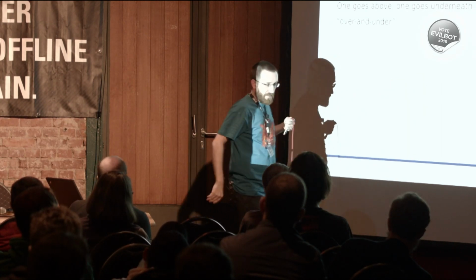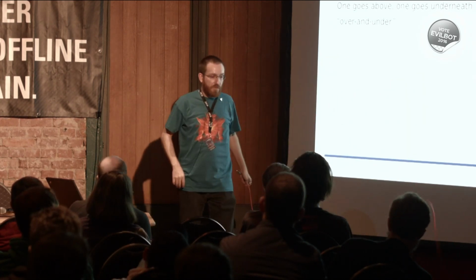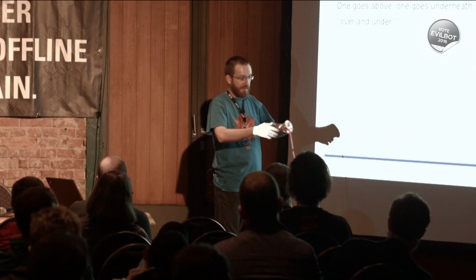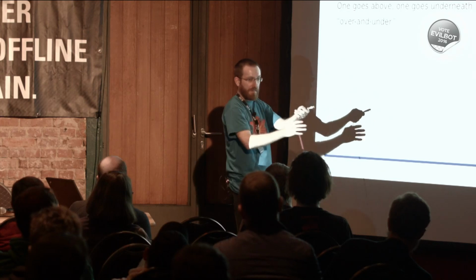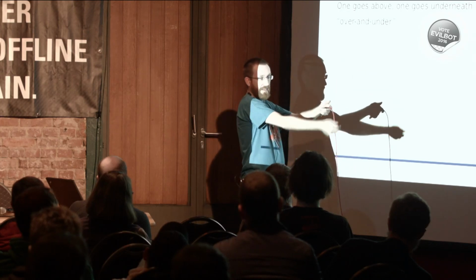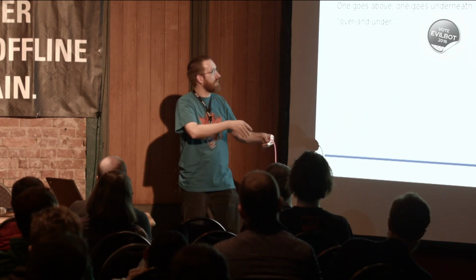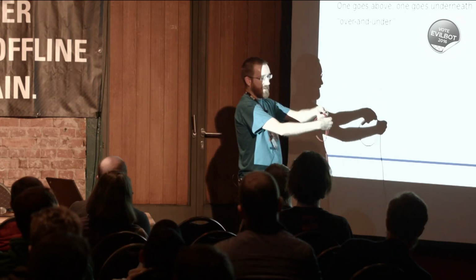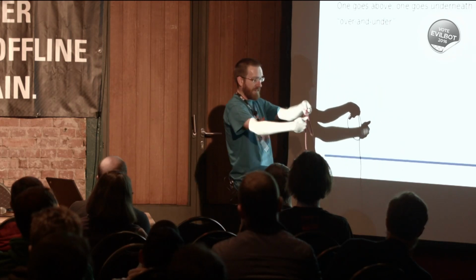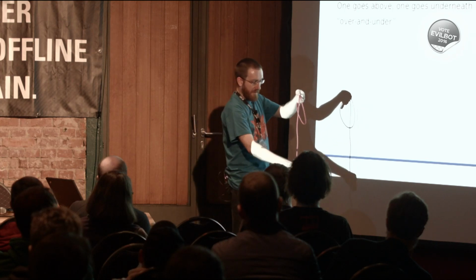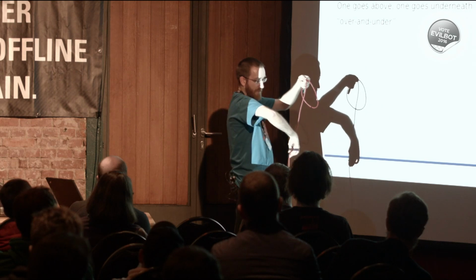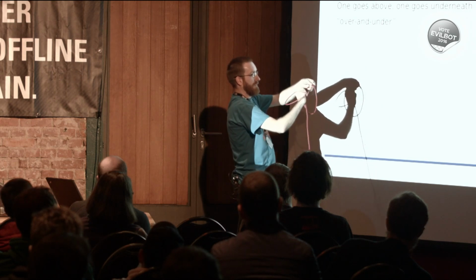The proper way to do that is to have a counter motion for this. And you can do this in either style. Some people prefer to wind like this, some people prefer to wind like that. The style is called over and under. You have one thing that goes down here, so this turns the cable in this direction. Now comes the under part. That's the new thing. You take this one and you go this way.